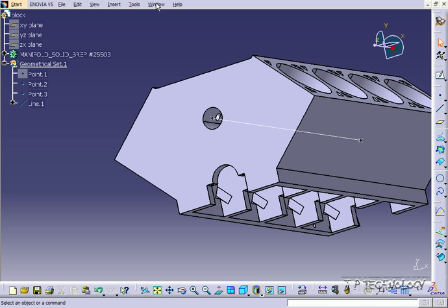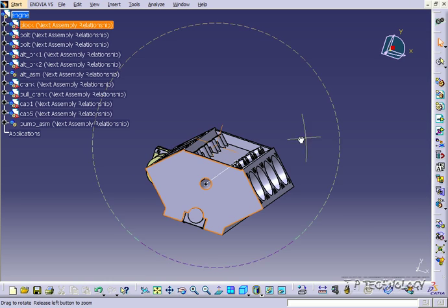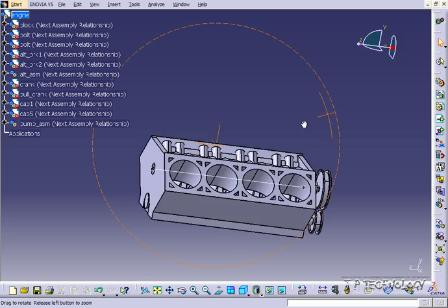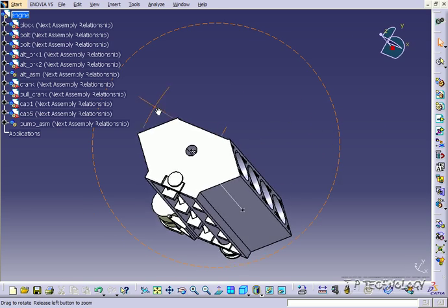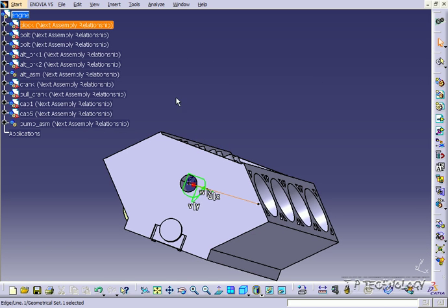So now let's go back to the entire assembly. Now we have our axis line, so let's throw our compass on it. So zoom into it and throw the compass and make sure that it's right on it. You'll know when it's on it when it snaps to that line. And let's double click and go into the properties.